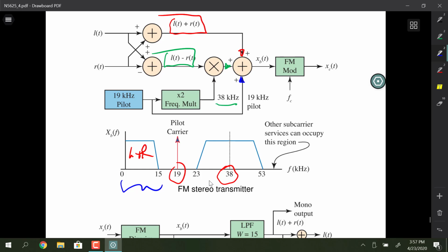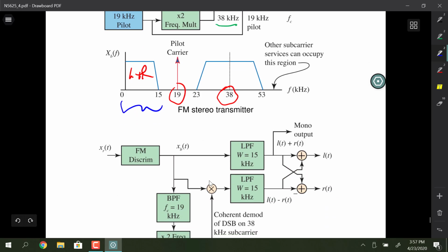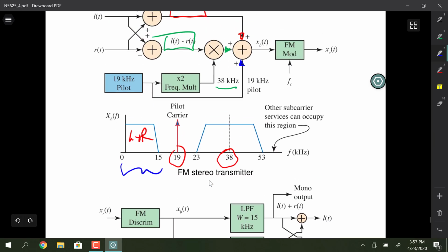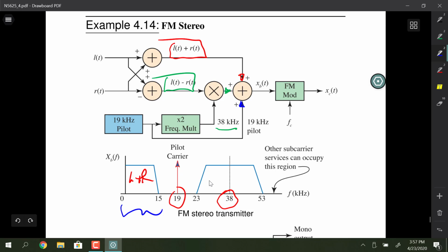So it's guiding. Can I ask a question? Sure. So I'm looking at the diagram for the left and right because that's actually something that I've been curious about. Okay. So you frequency multiply either the left or the right so that they have two different independent spectrums, and then you have a demodulator at the end that's looking for two different frequency bands. Is that right? Kind of. We don't multiply left and right together, though. We add and subtract them.